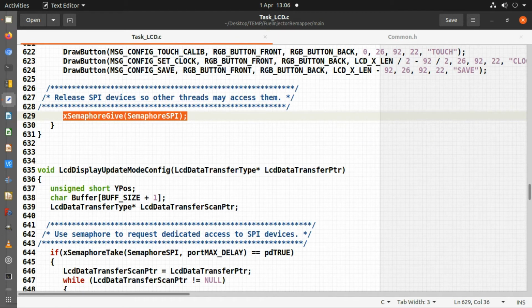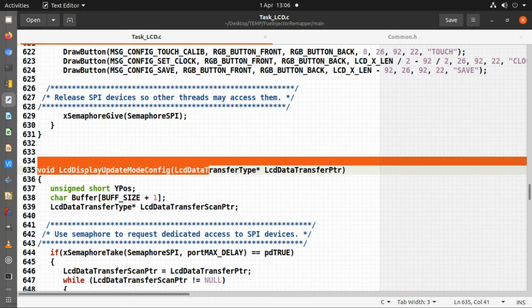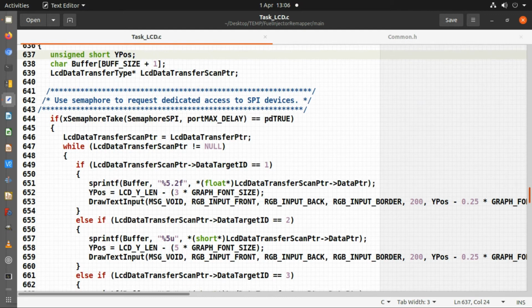So this next function here is the update. After the actual display new screen, in the source code you'll find the update function that is associated with that screen as well. And as you can see, it passes in the data, a pointer to the data within that. This function is quite considerably different to the previous function, because all it is doing is updating the controls to display what data is associated with those controls.